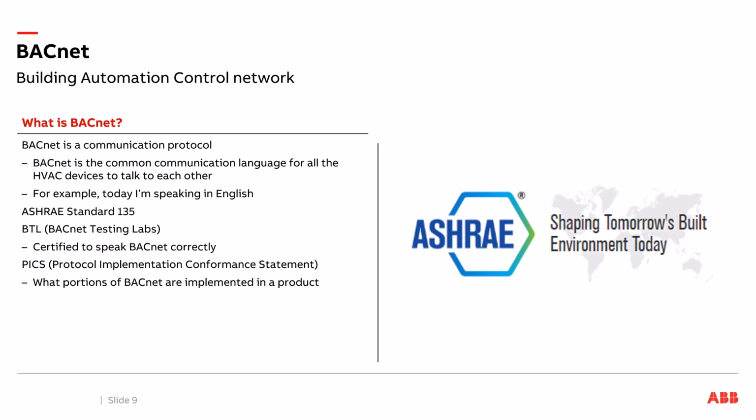So there's BTL, BACnet Testing Labs, and that's what we will do is take products and send them to be certified to make sure that we're talking BACnet correctly. So that way somebody doesn't just say, well, I have BACnet, but didn't actually get it BTL certified. You don't know if it's really communicating BACnet correctly. And then there's something called PICs. Again, I'm not going to do a deep dive on this, just giving a general overview of some of the things you might hear of in BACnet. Protocol Implementation Conformance Statement, and it really talks about what portions of BACnet are implemented in a particular product, and I'll show you an example of that later.